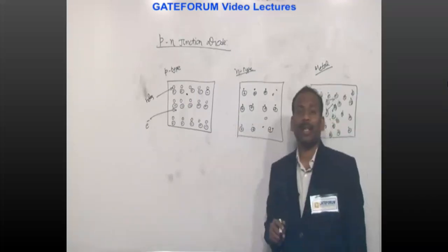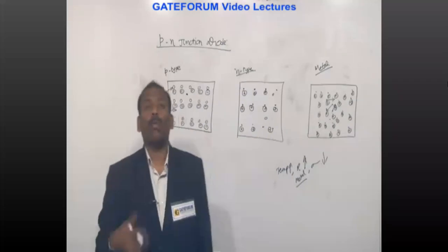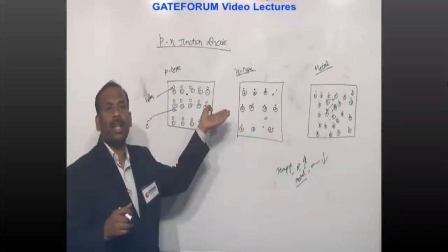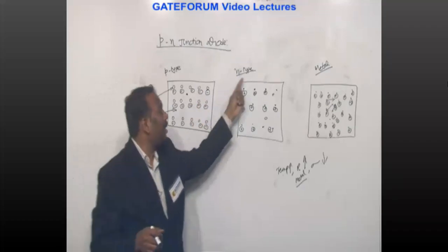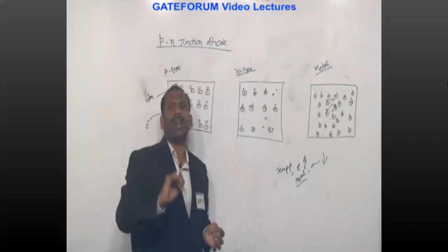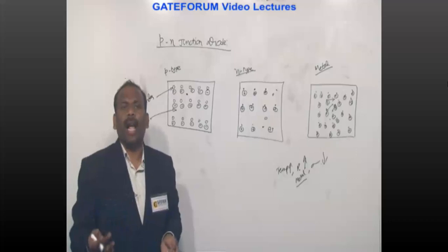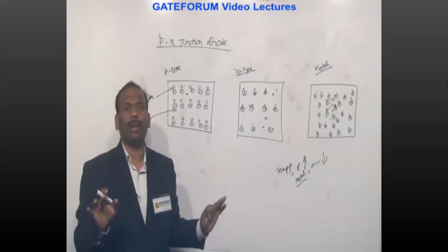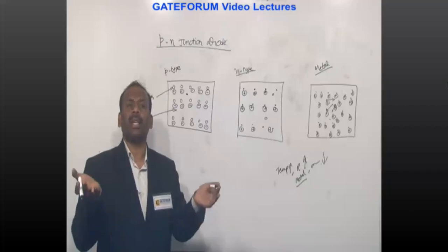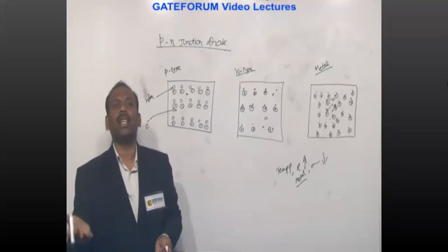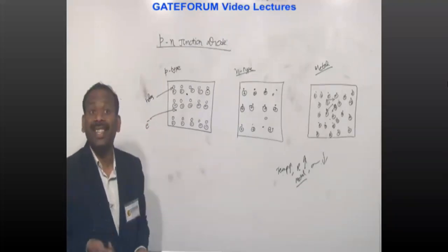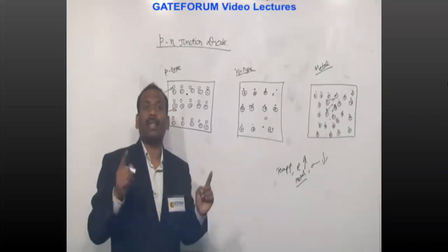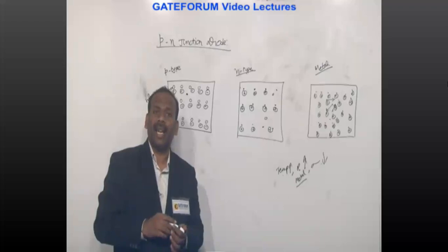Whereas in semiconductors, as temperature increases, more covalent bonds are broken, and the numbers of electrons and holes increase. Initially there are fewer charge carriers, so increasing them further is no problem because area is available. If we increase the temperature, the number of charge carriers increases, current increases, resistance decreases, and conductivity increases. For semiconductors, as temperature increases, the number of charge carriers increases.